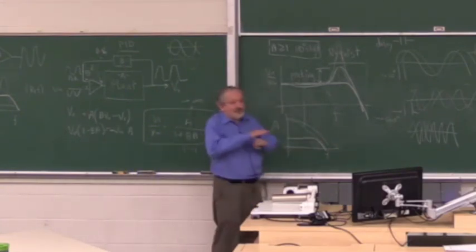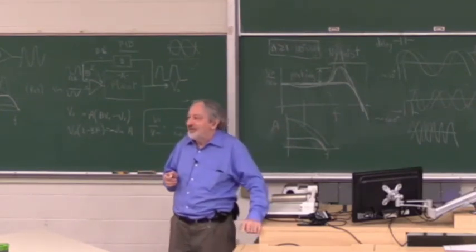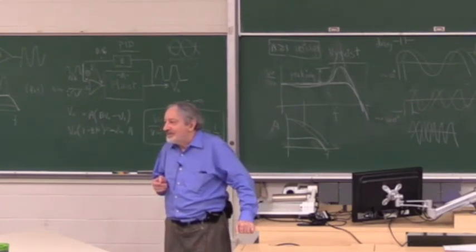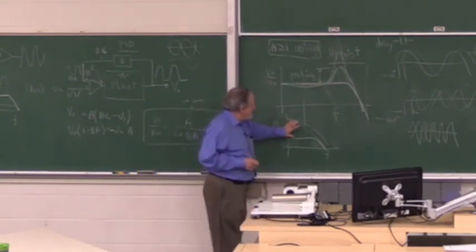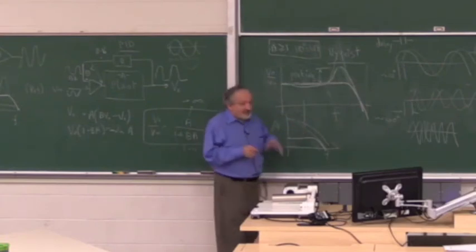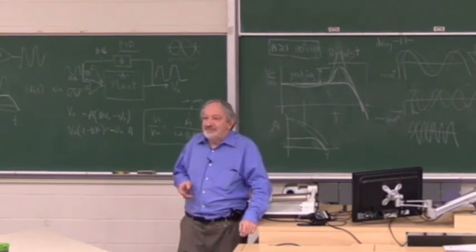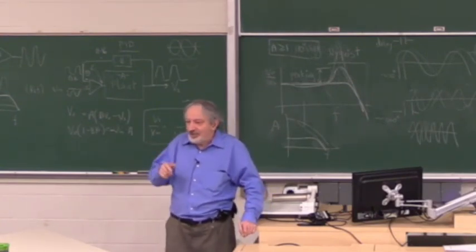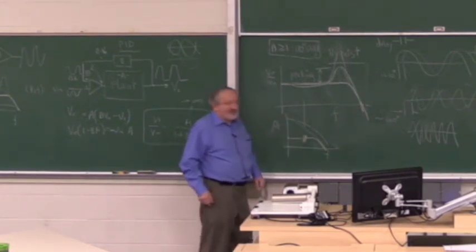You are closing the loop. It will hold the gain constant. But when you try it, it doesn't work. The errors between the signal and the reference and the output will get higher at this point. But let's say you have plenty of open loop gain. So the errors get higher, but the servo should suppress them, just like it suppresses distortion. But in reality, if you have a resonance and you close the loop, it doesn't behave like this. It actually goes crazy where the resonance was.